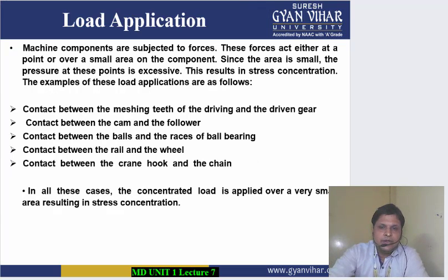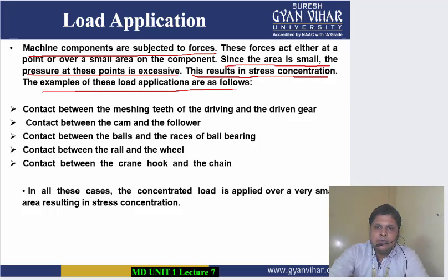Second important factor for increasing stress concentration is the load application. Machine components are subjected to forces. These forces act either at a point or over a small area on the component. Since the area is small, the pressure at these points is excessive. This results in stress concentrations. The examples of these load applications are as follows.